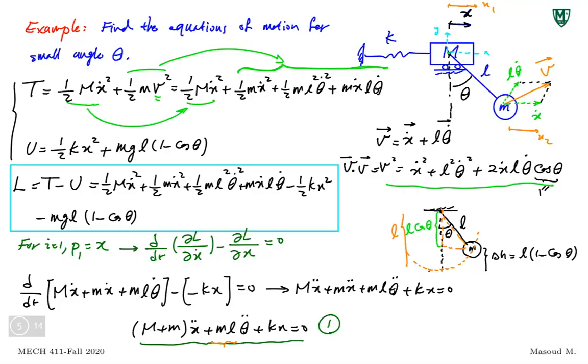I haven't done this with this coordinate system, but you might either get a coupling because the mass matrix non-diagonal elements are non-zero, or because the non-diagonal elements of the stiffness matrix are non-zero. So depending on what you take as your coordinate system, the coupling changes.